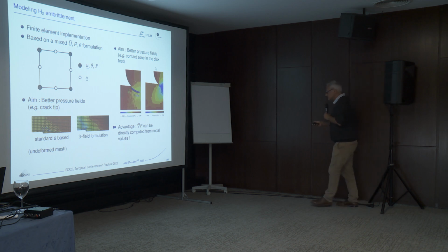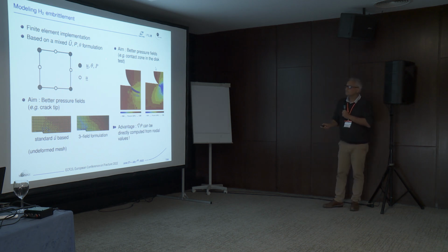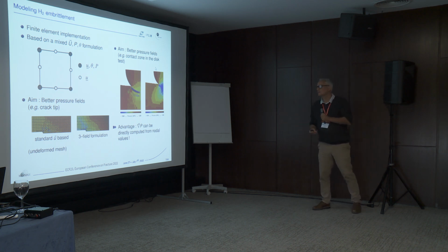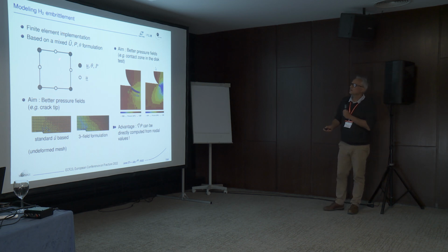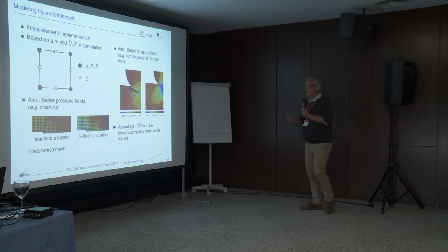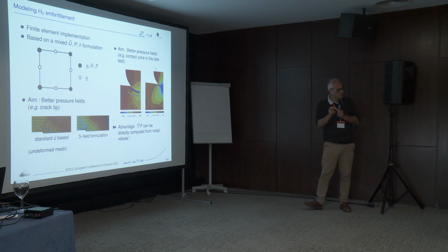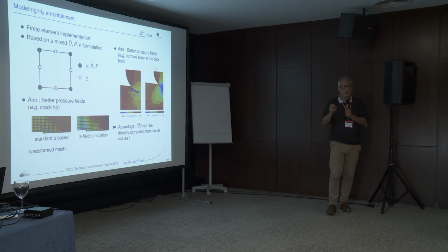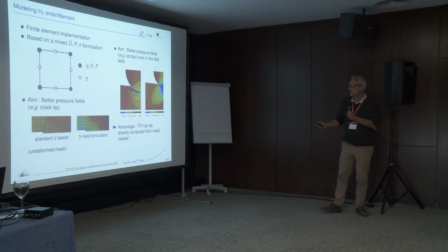So what is a little bit more new in this presentation is the way we implemented this model. We have a finite element implementation. We use finite strain. It's obviously necessary if you see the deformation of the disk. But the implementation is based on a mixed element using displacement, pressure, and volume variation.